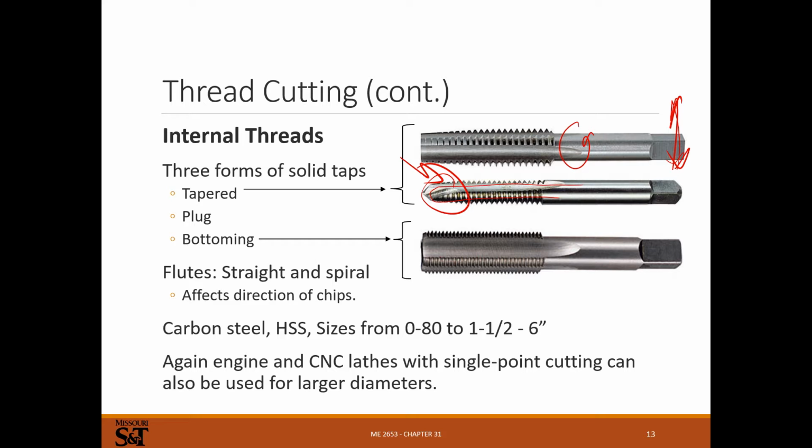I've seen some old pro machinists tap holes all by turning the mill on with a tap in it, turning it off, and then pulling the quill down and starting the threads. Then they just use the inertia of the mill to continue to tap through, and they might bump the motor on a couple of times and then reverse it to back it out.